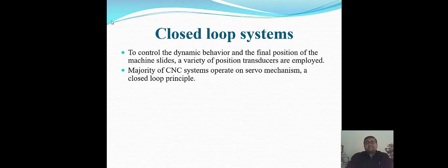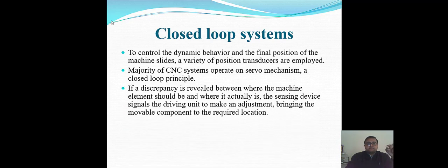Majority of the CNC systems operate on servo mechanism, a closed loop principle. Here there is a crux: servo motors are used for precision, and if servo motors are not used, then a stepper motor cannot give the accurate result.